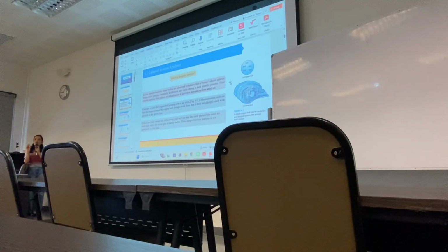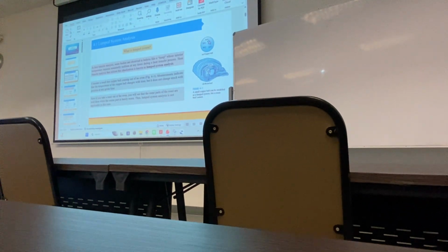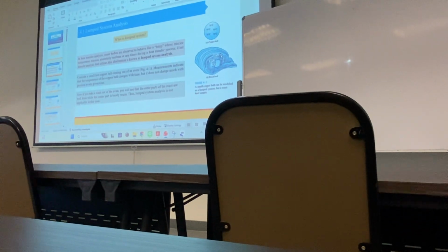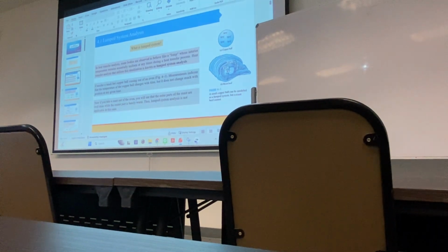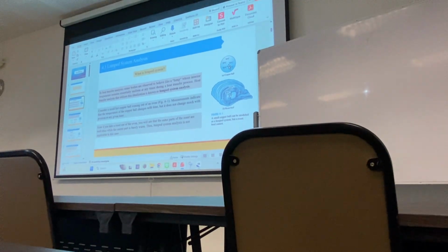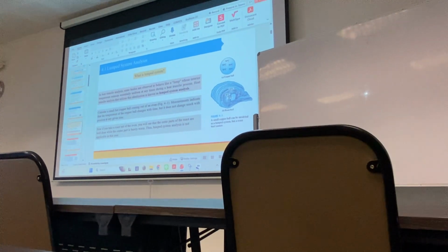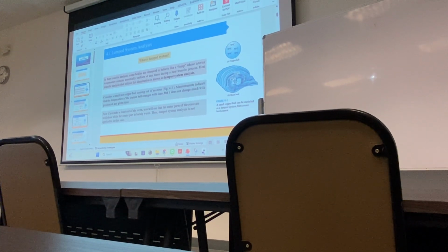So in chapter 4 we have two types of system. One is a lump system in which the temperature changes with time but stays the same at every position. The second body is a non-lump system in which the temperature changes with time as well as position in the system. So this copper ball was an example of a lump system and this was a non-lump system. So we had two types of bodies. Then we derived the equation for lump system analysis.